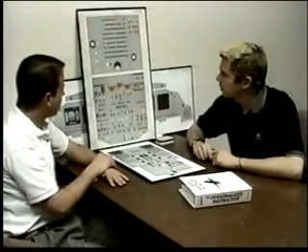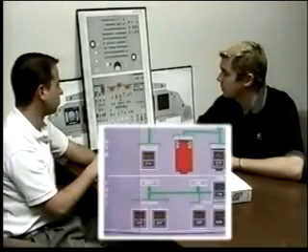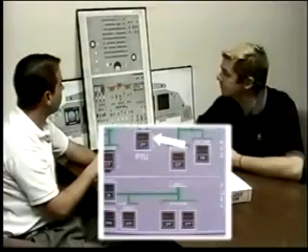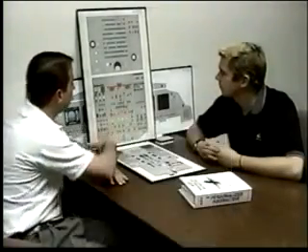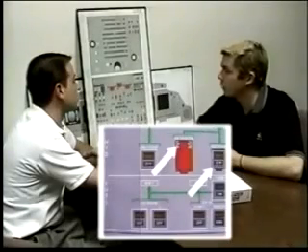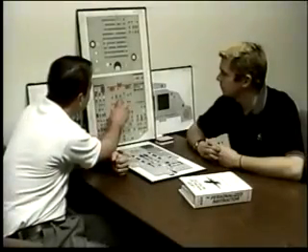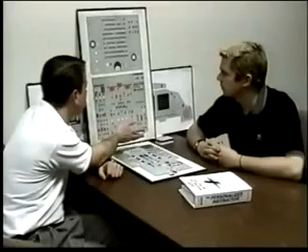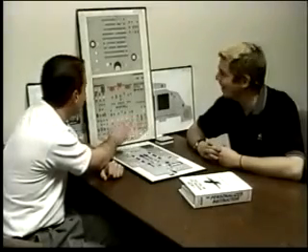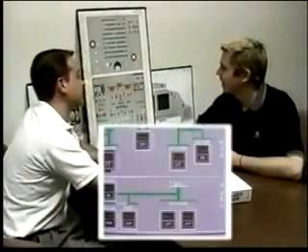Hydraulic panel. Starting with the green system, how many ways to pressurize the green hydraulic system? Just the engine-driven pump. Anything? And, well, the PTU backs it up. How many ways to pressurize the blue hydraulic system? Either the electric pump or the ram air turbine. The blue electric pump, with the switch guarded and the switch in auto, when does the blue electric pump begin to pressurize the system? Let me see. First engine start? Very good. First engine start. Amazing.